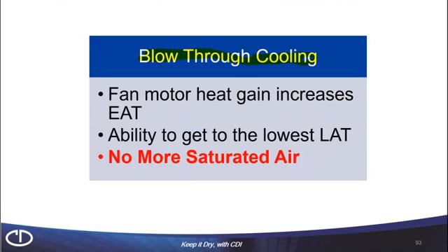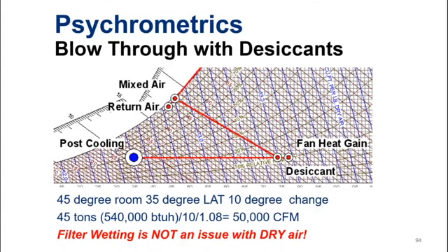You can get to a lower leaving air temperature, and you're not going to have saturated air. So if the system has final filters, those filters will not become wetted, as the air would have a pressure drop across the filter and therefore leave moisture in the filter if it were 100% saturated. So no more saturated air. You can have dry filters downstream.